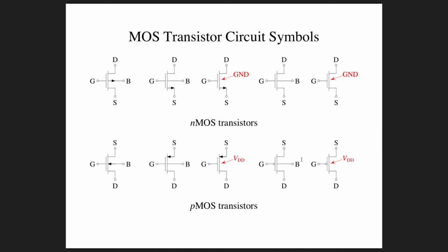These symbols over here are the ones that I prefer and the ones that I'll be using. And these grew up in the context of CMOS digital circuit design. And the convention is that the NMOS transistor does not have a bubble on the gate, but the PMOS transistor does have a bubble on the gate. Okay, so in digital schematics, usually the bubble on an input or an output denotes that an input or output is inverting, so that the output has to go low for the device to turn on. And that's the way in which we're thinking about the bubble here on the gate.